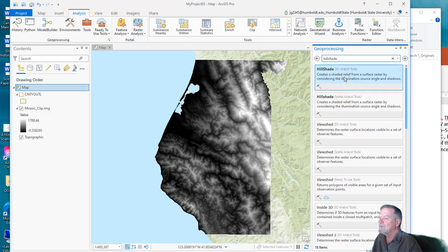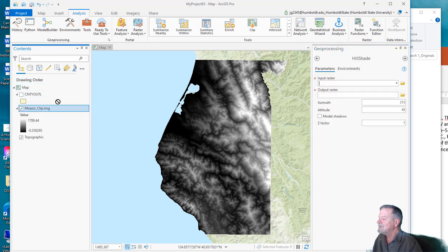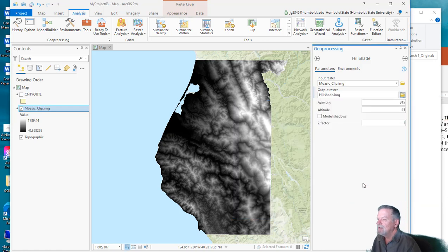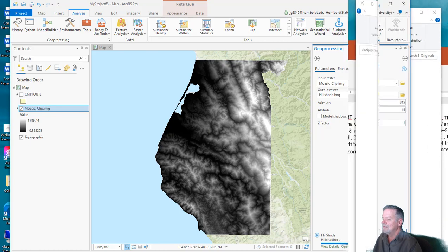Now, when I went through this lab before, I actually did this at every step since we've been having issues with hillshade rasters, or with DEMs having artifacts in them. I ran hillshades regularly, and made sure that they looked good. And you can't do enough hillshades to look for artifacts, in my opinion.